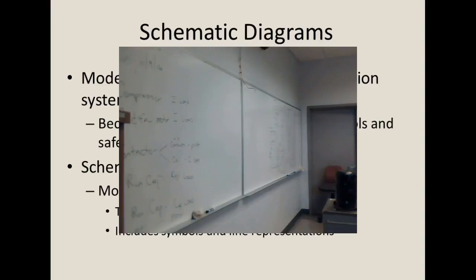A PSC motor or split phase motor, sometimes a single phase motor. Single phase, split phase motor, same thing, just different terminology. A PSC motor, what we use most of the time, is a type of single phase or split phase motor, because PSC means permanent split capacitor. In other words, it permanently has a run capacitor attached to it. Capacitors, as we saw from this diagram, always are wired up to the start terminal.